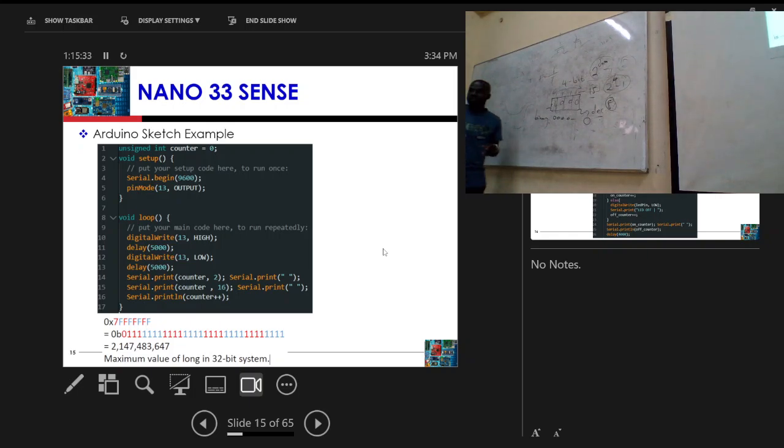So very important in digital systems or digital logic, the first value is very, very important. It is known as the MSB, the most significant bit. And the last one is known as the LSB, the least significant bit. For signed numbers, we use the MSB to identify whether it's negative or positive. So once I'm doing the calculations, the first number is out. I can't use that to tell if the number is 1 or 0. It's out. So I use this one to identify.